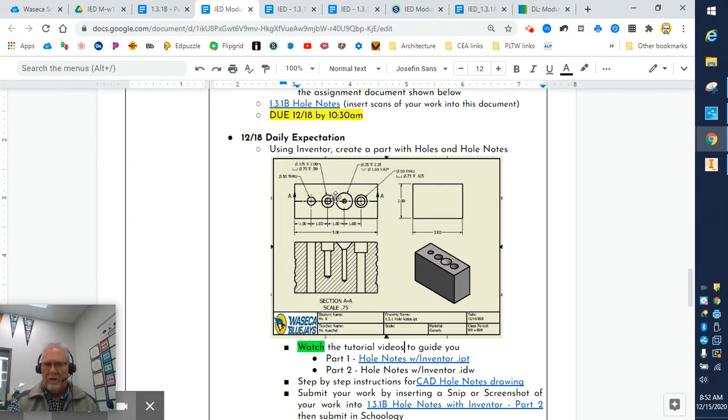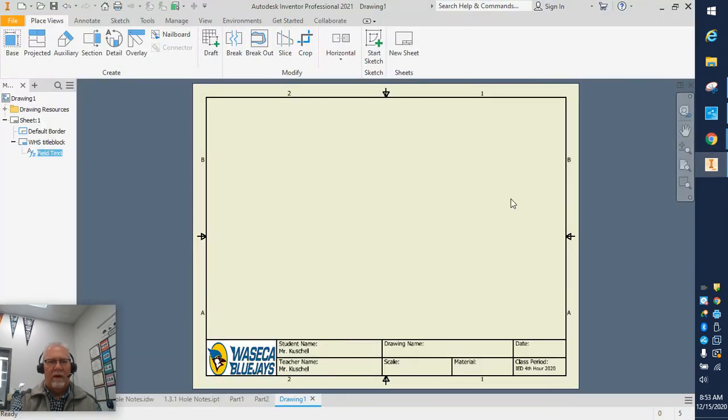We're going to show the section view as the bottom, technically, of our drawing, because if this is our front and this is our side, top would go above that and bottom goes down below. For the sake of what we're doing, I want to be able to see the holes, add hole notes, but I want to see a cross section of this to see exactly what that looks like. That should look similar to the view that we've been bouncing in and out of with Inventor.